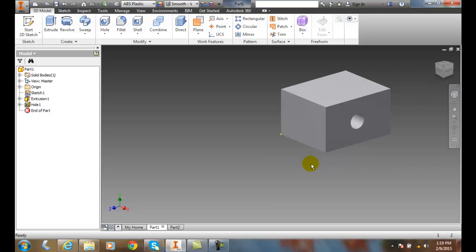We have rotational, so it spins. We have a slider that goes back and forth, up and down on a particular path. We have a cylindrical, which allows it to go around an axis of a cylinder. We have planar, which means, like on a sheet of paper, it can go in two different directions, up and down, left and right. And we have a ball joint, which means we can create a ball and things will rotate freely around that ball. The two remain in touch with each other, but they are restricted at a common point.